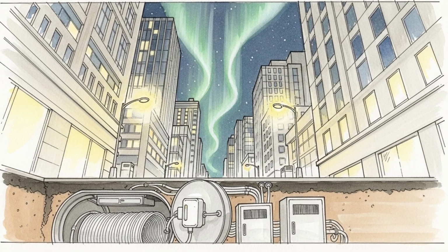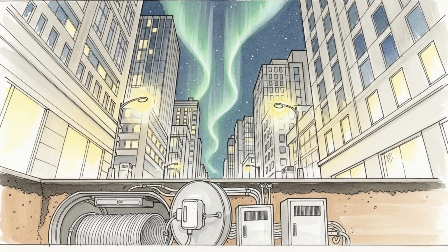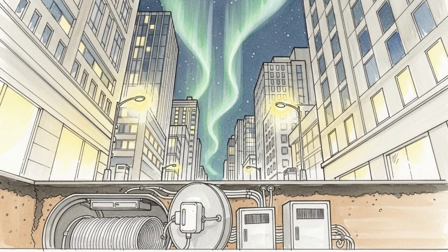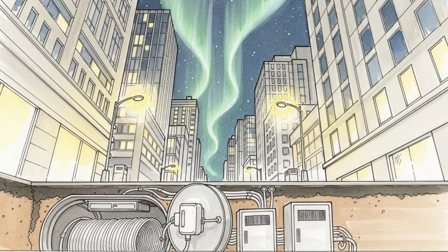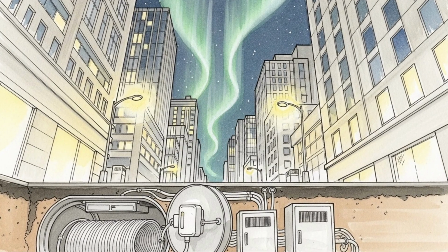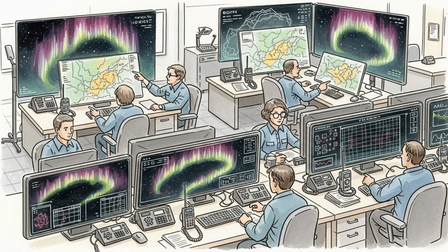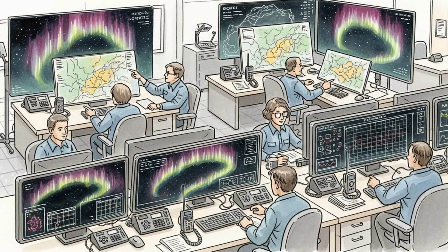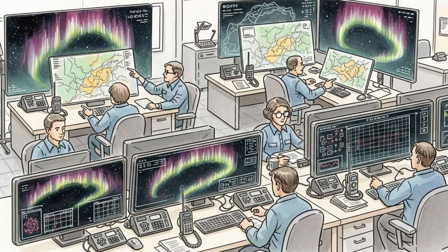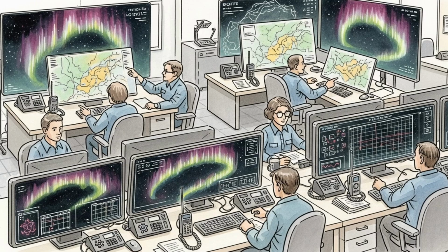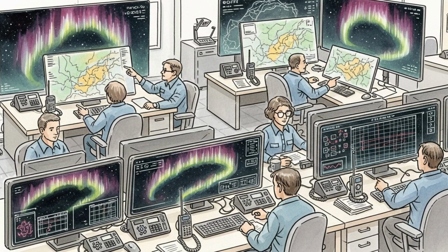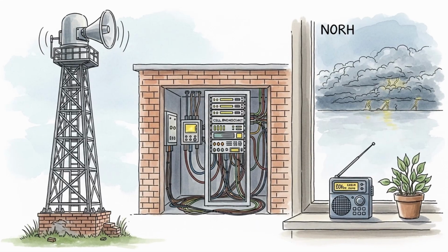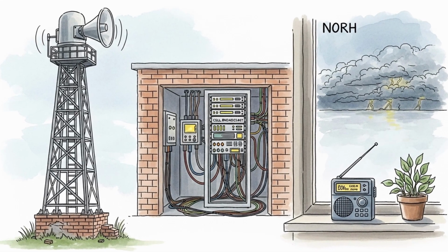Large power transformers are the main bottleneck. Geomagnetically induced currents add a direct current bias to the windings. The bias drives the magnetic core toward half-cycle saturation. When saturation begins, magnetizing current rises, waveforms distort, and additional heating appears in structural parts and windings. The effect is not a conventional short circuit. It is a bias that makes normal operation inefficient and hot. If many large units enter partial saturation at once, the system needs much more reactive power to hold voltage.